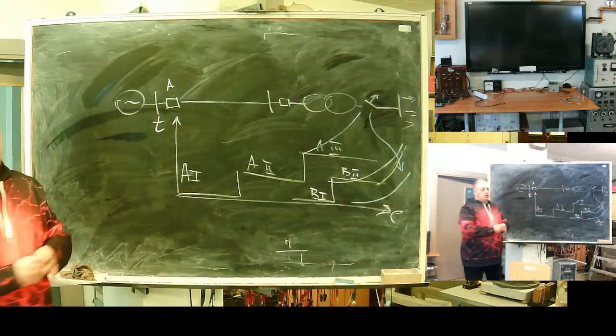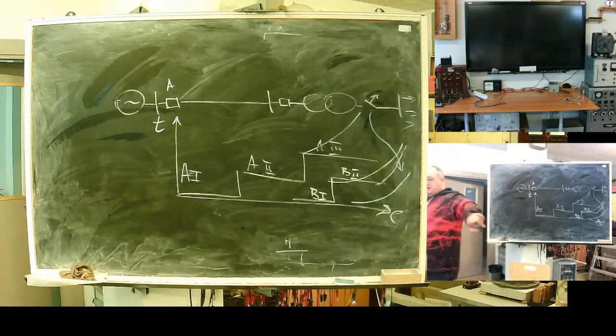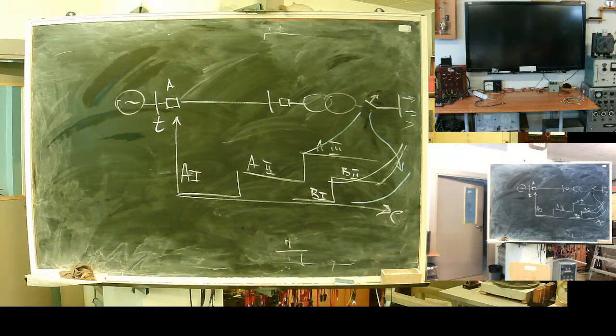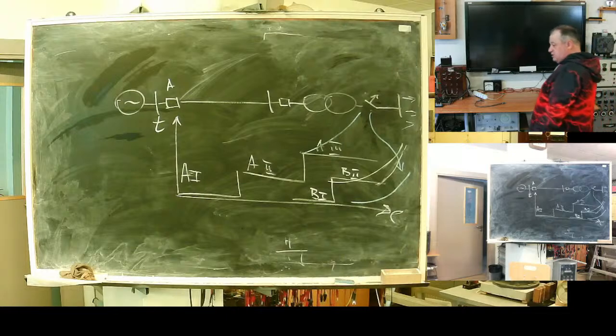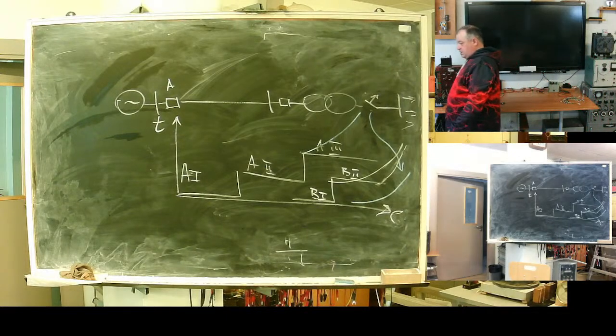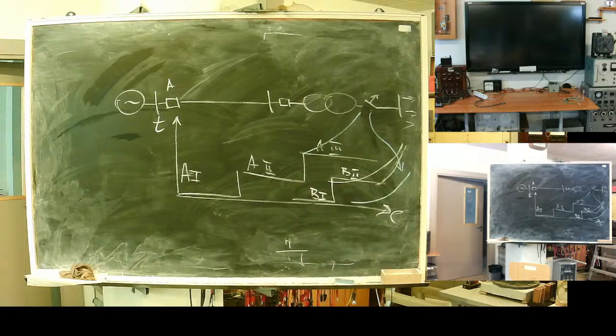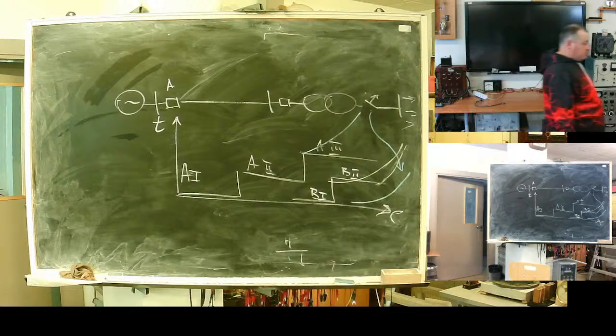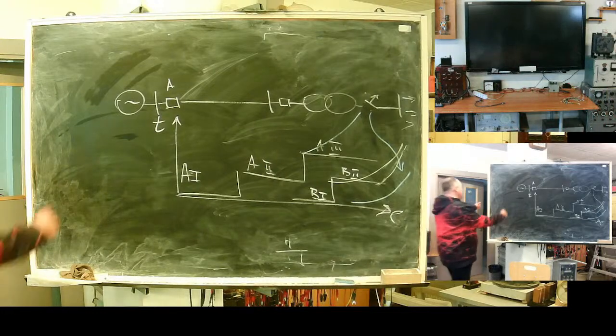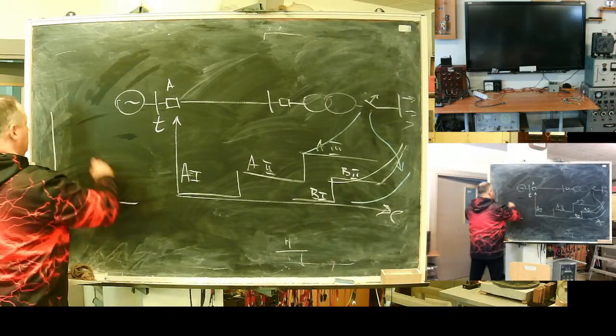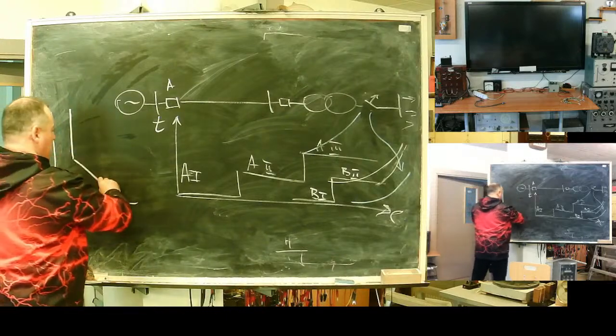This is a solution to the problem of this inrush characteristic and overload and the necessity to coordinate with fuse and low voltage circuit breaker with thermal protection, even digital, yes, you can find modern digital, you may face